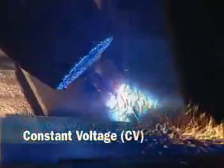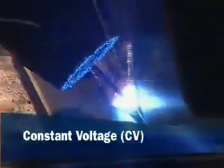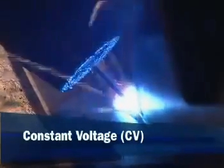CV welding typically allows short circuits in the arc. The shorter arc lengths attainable in CV meant faster travel speeds for manufacturing. AccuPulse and its variations allow the combination of spatter control and faster welding travel speeds by using both CC and CV in the same pulsed waveform.